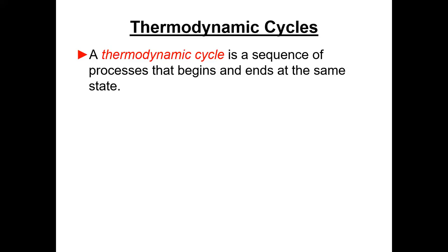If you look at the working fluid, the water, say it's liquid, it gets vaporized into steam at high pressure, it goes through a turbine to low pressure, it comes out, it's still mostly steam, it gets condensed, and then it gets pumped back, and it comes back to the same point. Exactly the same condition at which it went into the boiler, and that working fluid keeps going through those 4 processes all day long, and the net result is we make electricity out of the cycle because that turbine is turning a generator.